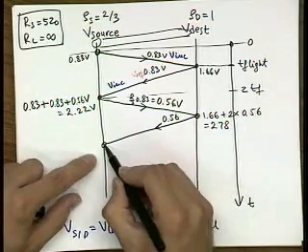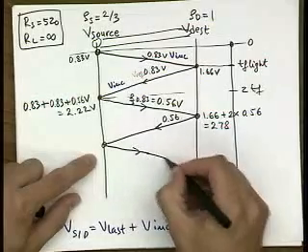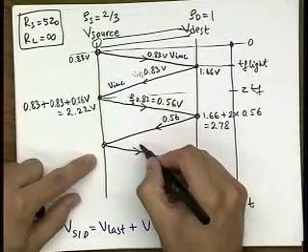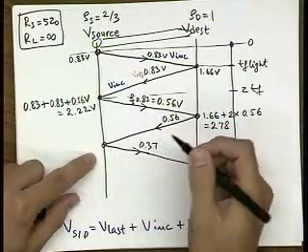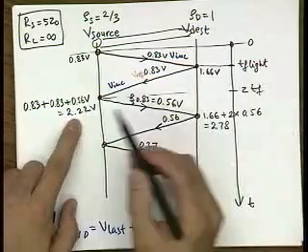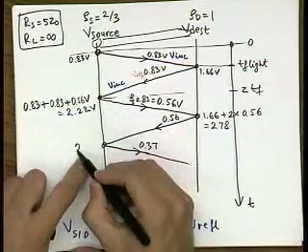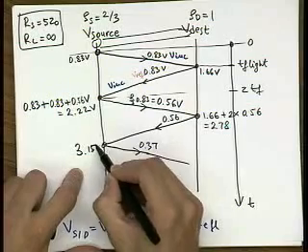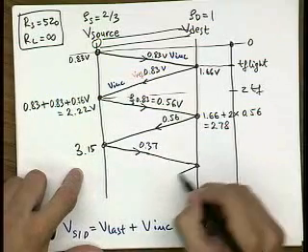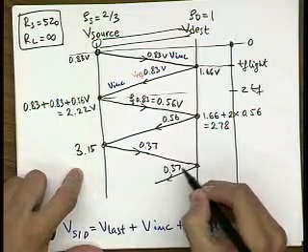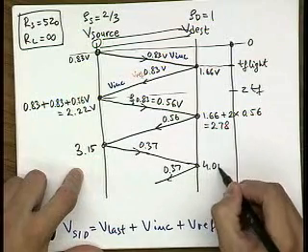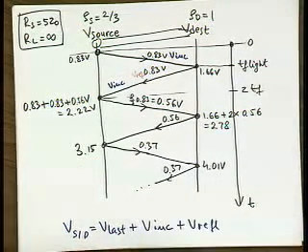Now 2/3 of this gets reflected back, so this is 2/3 times 0.56, that's 0.37. This is now the previous value plus these two, which becomes 3.15. Then you have 0.37 reflected back, you have 4.01, and so on. So now you understand the methodology, the way you analyze the transmission line.